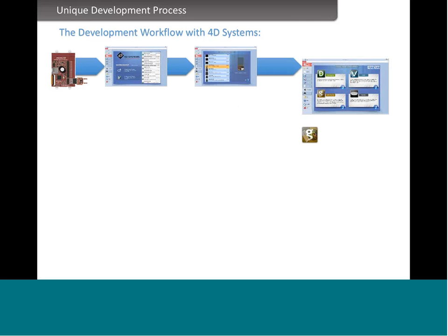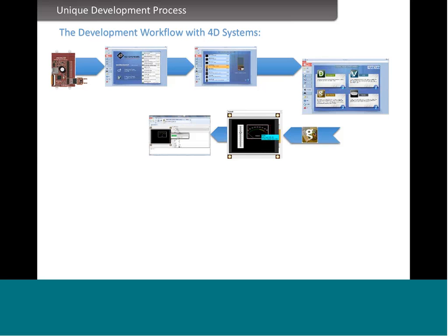So the quickest way to create a GUI is the ViSi-Genie feature. You can use widgets and drag and drop them into a display, a graphical picture in the IDE environment. And when you're finished with the graphical environment, you can just build your project.